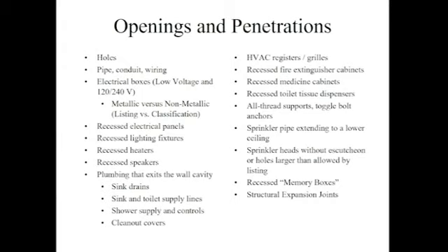UL, who's typically, there are other testing agencies, like I had mentioned before, that do classification or rather listings for various products. But UL does the majority, at least that I have seen, of metallic and non-metallic electrical boxes. We're talking 4x4 or your typical single gang, which is like an inch and a half, 2 inches by 4. And the metallic boxes actually all have their own listing. They're all grouped together as a single product. And then there's a guide info by UL that tells you exactly what those listing requirements are.